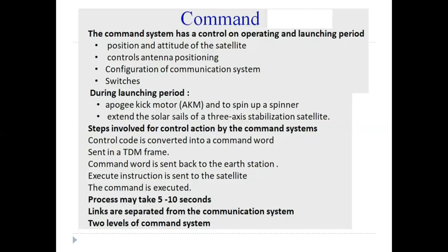With these controls, the satellite can be injected into the geostationary orbit, turned to face the Earth, and switched to full electric power so that handover to the main TTC and M system is possible. In the event of failure of the main TTC and M system, the backup system can be used to keep the satellite on station. It is also used to eject the satellite from geostationary orbit and to switch off all transmitters when the satellite eventually reaches the end of its useful life.